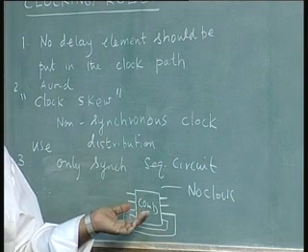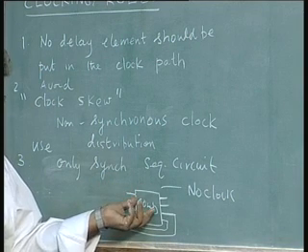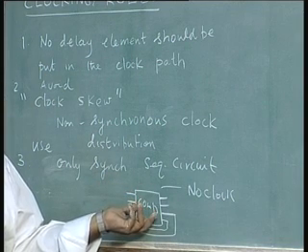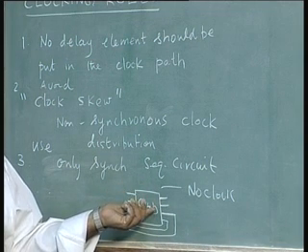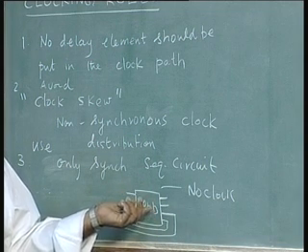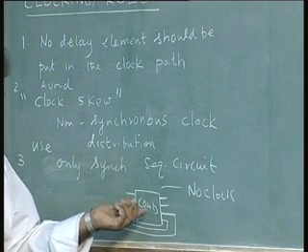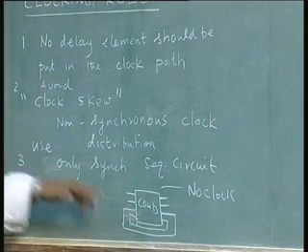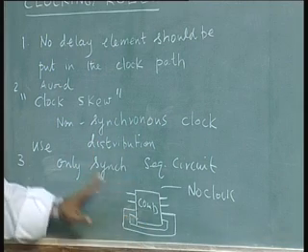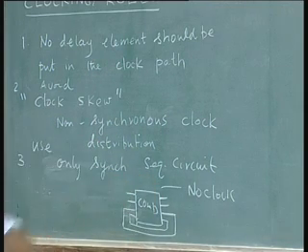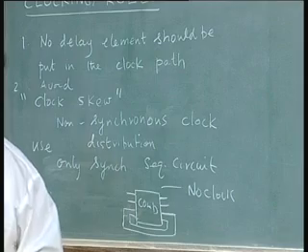So, there is going to be chaos inside this, especially when more than one input changes at the same time. The circuit behavior is not completely controlled by us. This is a problem. This problem can be avoided only by putting a clock. If you have a clock, the transition will occur at a given time.